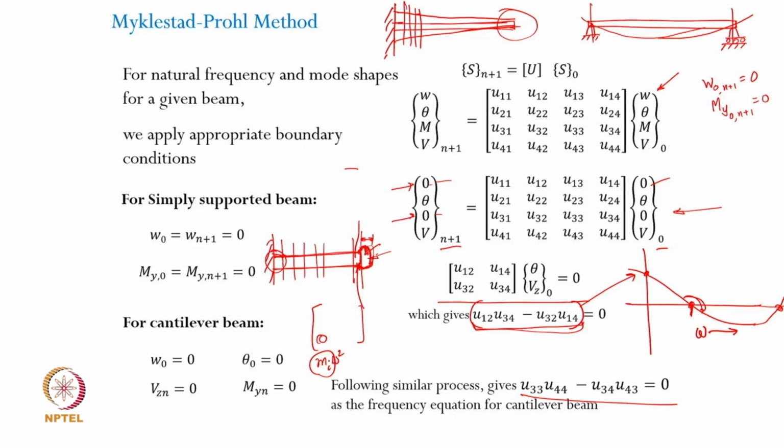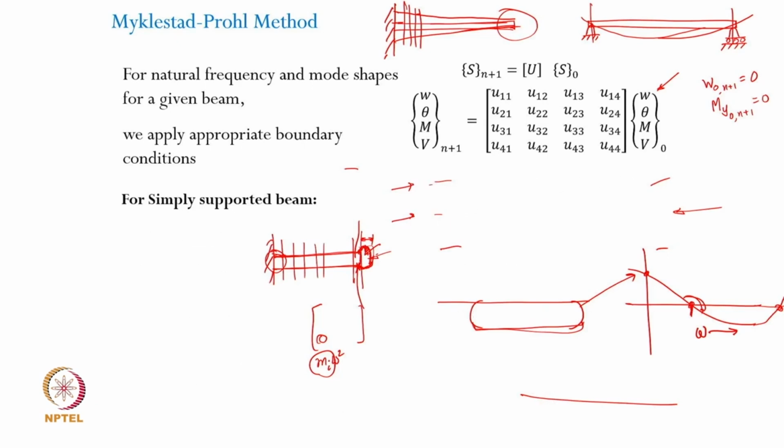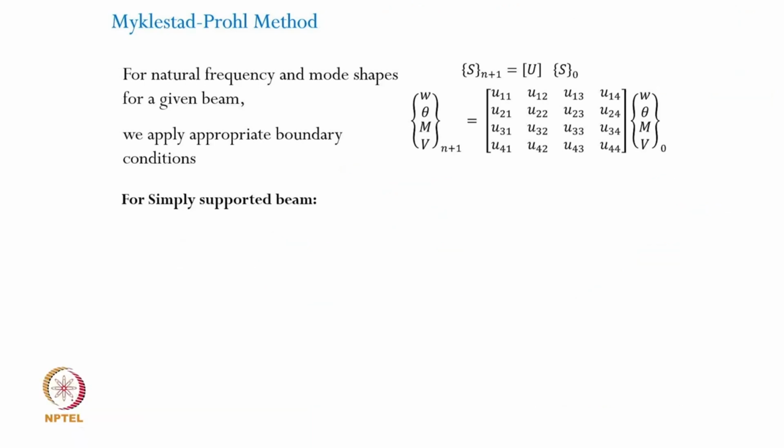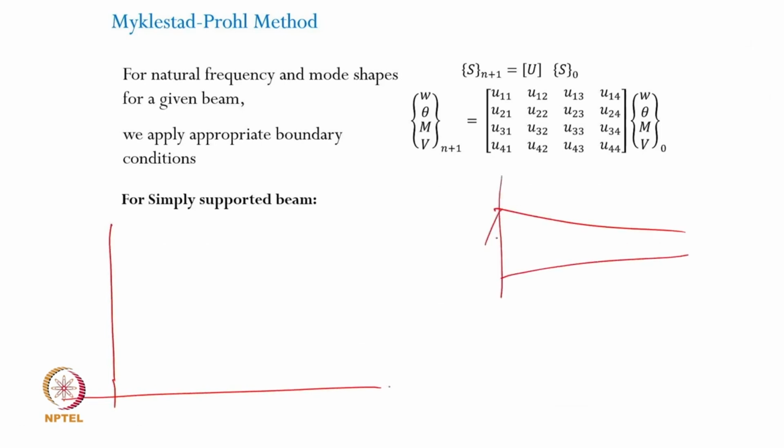So therefore, what is the effect of discretization? Okay, what is the effect of discretization? I mean, that you plot, you first discretize this tapered beam, okay, a turbine blade, into, let us say, 10 number of segments. So you will have these 10 segments here, and with 10 segments, so I will write this as n, which is representing number of segments, and you evaluate all the natural frequencies, omega i.